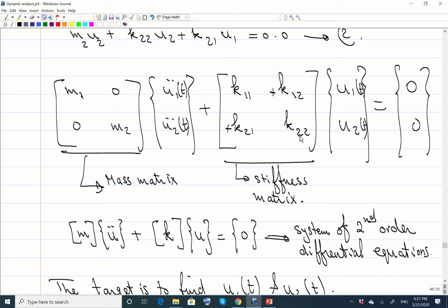Definitely, if you're just interested in the horizontal displacements, the only displacements that you have are u1 and u2. You can start with a very large stiffness matrix, and then do static condensation until you get just u1 and u2, as we did at the start of the semester, okay? At the start of the semester, we had a single story frame, and there were actually 3 degrees of freedom. We eliminated 2 by static condensation. We only had the horizontal displacement of the first floor.